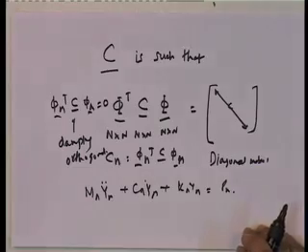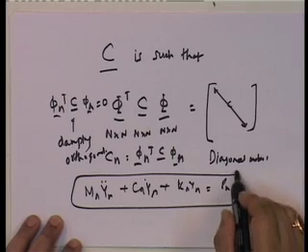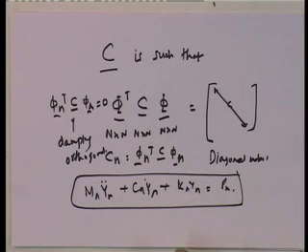So, that means it is orthogonal with respect to the damping. Remember, we already showed that it is orthogonal with respect to the mass matrix, it is orthogonal with respect to the stiffness matrix. Now, we are saying that for us to ensure this, which is the uncoupled modal amplitude equation, we have to have the mode shape vector also orthogonal with respect to the damping matrix.